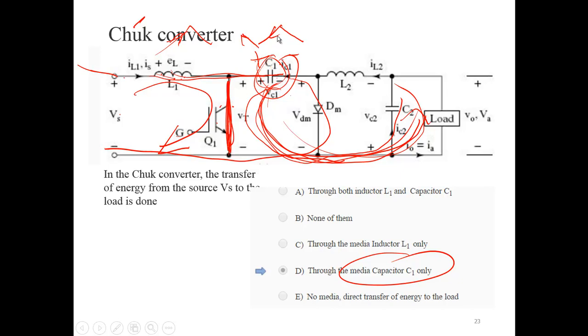As a result, the capacitor voltage will be positive, then negative, and the current will sometimes flow this way, sometimes the other way. The capacitor current will be AC, alternating. You don't get a DC current; one time you get a positive direction, another time the opposite direction. This capacitor has to take all the energy, transfer it, and give it back.